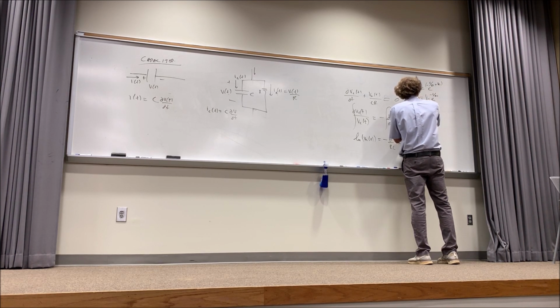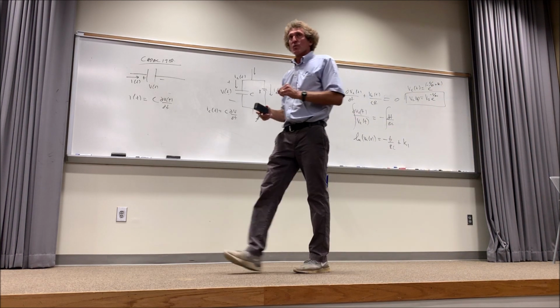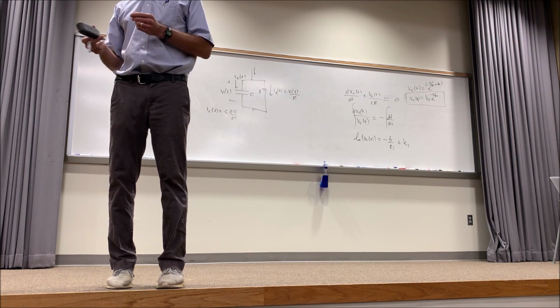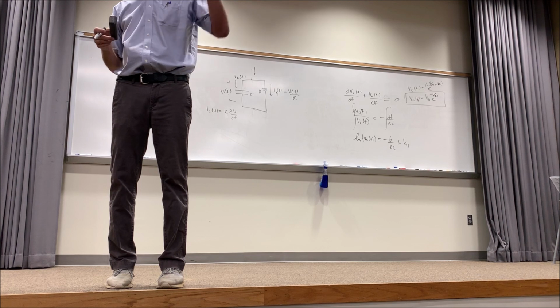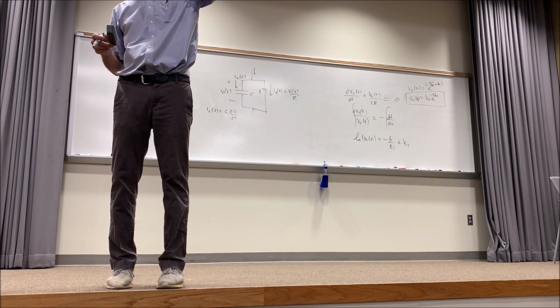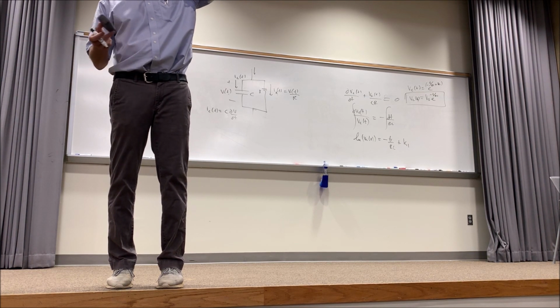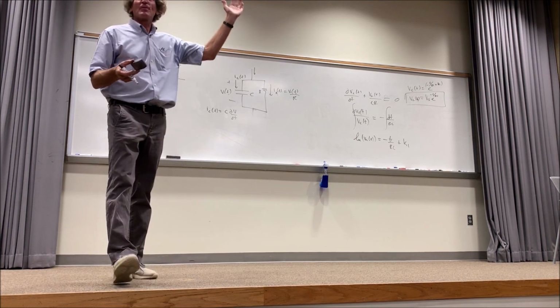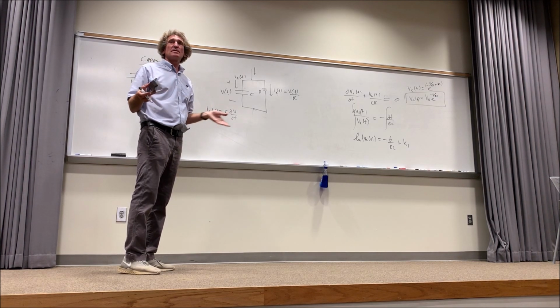Now that's the general formula for voltage on a capacitor with only a resistor in parallel and nothing else added. Do you understand that? And what do you see there? That's exponential decay. At t equals 0, if there was a voltage V naught, it would exponentially decay to 0, correct, class? And how many remember this from physics? Or high school physics, or whatever you had in electronics? This is the equation I had, I think I was a sophomore in high school. So this is stuff that we've all seen many, many times in many different ways, right?